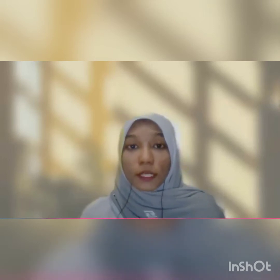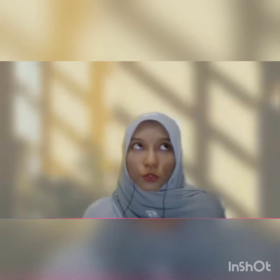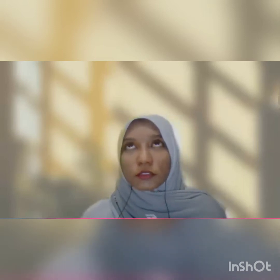Okay, next I will talk about Taguchi's method in experiments. In experiments, Taguchi's method is recommended because it can study a large number of variables in a small number of experiments. This method can help to determine the number of experiments that are needed with the factors provided and the level of each design in the experiment. The factors can be grouped into noise, control, inductive, block factors, and signal adjustment. The noise factor can come from three sources: first is unit to unit variation, the second one is external factors, and the third one is internal factors.